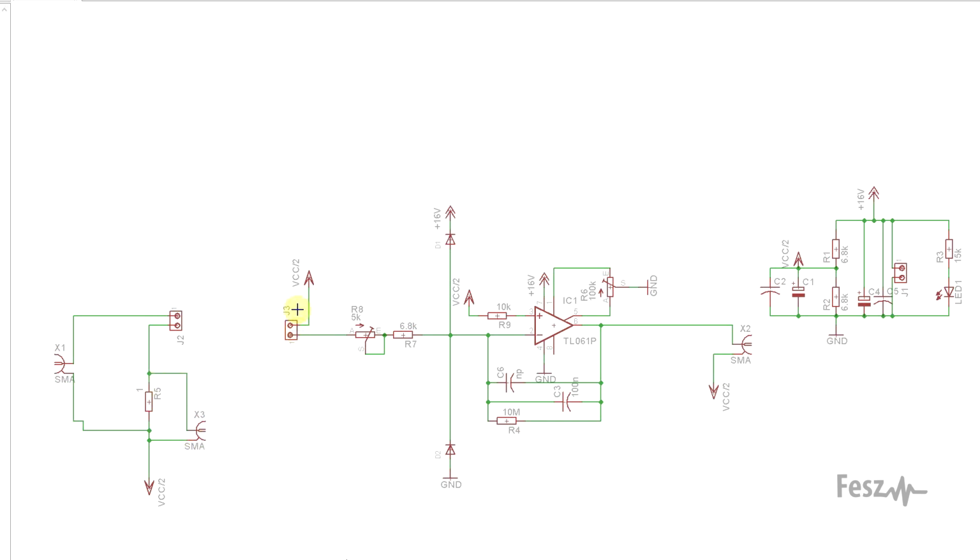And then on the secondary side, the secondary coil will be connected to this connector, and we have our op-amp based integrator circuit. Now here, we do have a few components extra to what we used in the simulator. So first of all, we have a set of diodes to protect the op-amp's input in case there's any sort of transient event. Then I added an extra trimming potentiometer for offset compensation, so this will be needed to calibrate the input to be zero referenced.